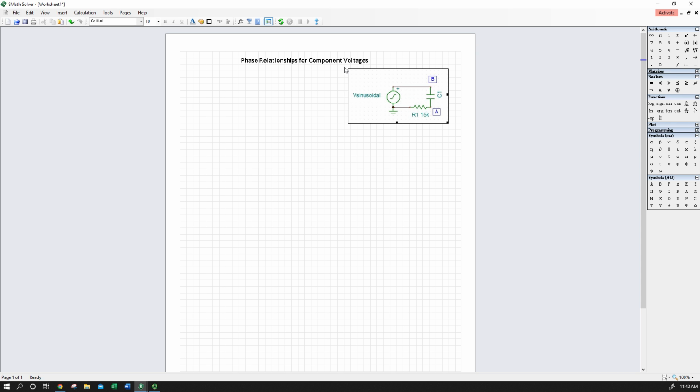The goal of our calculations is going to be to determine expressions for the voltage drop over either the capacitor or the resistor. Actually, we're going to do both, such that if we built this circuit on our protoboard, imposed a sinusoidal voltage signal, say with our picoscope arbitrary waveform generator, and then used our oscilloscope, picoscope or any other, to measure the voltage drop over either component, we could confirm that with our calculations. So we're basically going to build ourselves a calculation-based model.